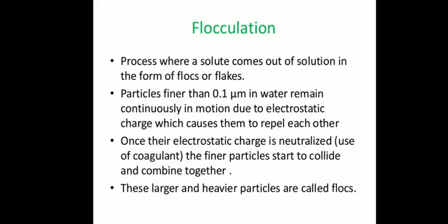Flocculation agents or flocculating agents are added inside the broth, and certain aeration and agitation is provided, so the floc formation takes place inside the broth and the solid material present inside the medium will get separated in the flocs. Now generally the finer particles of 0.1 micrometer in water remain continuously in motion due to electrostatic charges, which cause them to repel from each other. Once their electrostatic charges are neutralized, the finer particles start to collide and combine together.